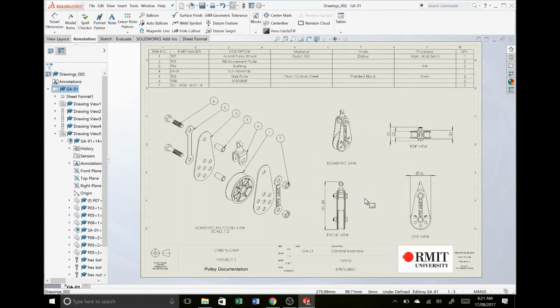Sometimes, particularly with dimensions, too much information is just going to complicate things. The manufacturer will think that that bolt has to be exactly 51.89. It will take them a long time to actually make it that accurate. They'll have to buff it back, and then they'll charge you for that. So, if it only has to be about 52 millimeters, then make sure that your dimension reflects that. Remember, it's about being clear and imagining what other people will infer from reading your drawings.